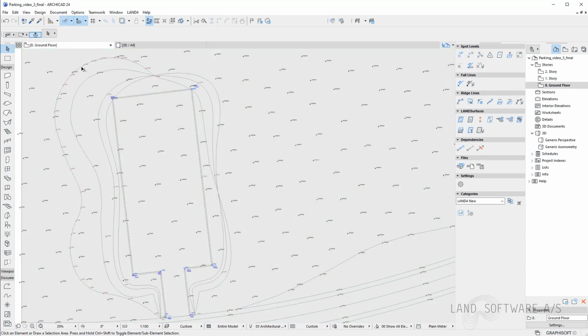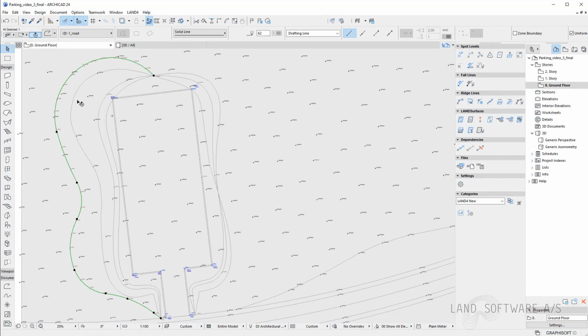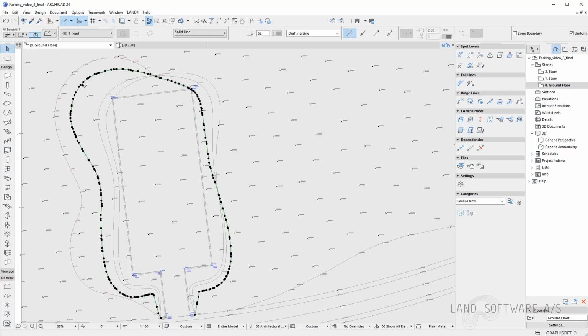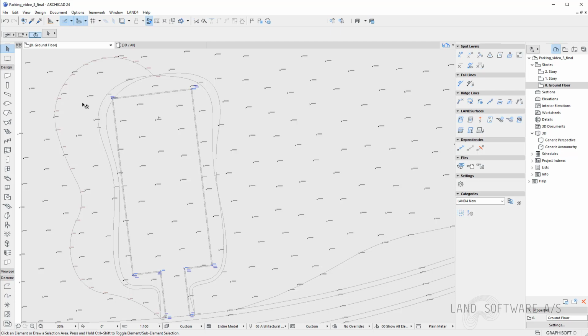And I can see that because I need more fill anyway on this area, and based on the existing terrain, which is lower on this side, I can already see that I will have basically more fill, which is going to help with my balance. Therefore, I will continue and use the line I drew myself. And it's also just an example to show you that you can use both methods.